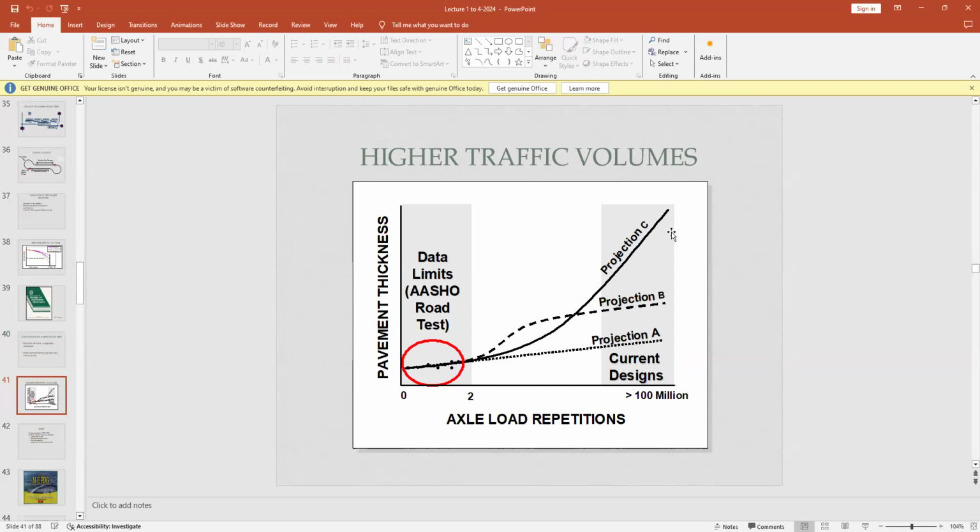So if you have 45 million traffic at the end of 10 years, and at the end of 12 years your cumulative traffic is more than 50 million, stop at 10. Even if you reach 50 million at the end of, say, 12 years, to be on the safer side, make it for 10 years. Even with computers, don't go beyond 50 million SLs, or you face failure.